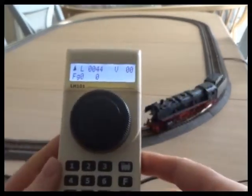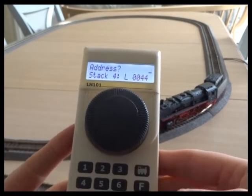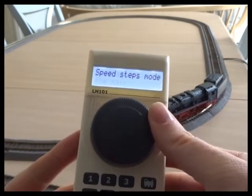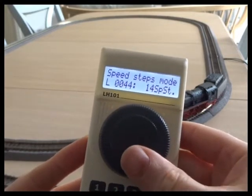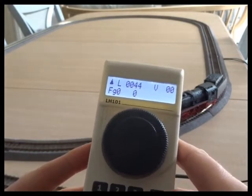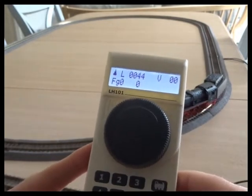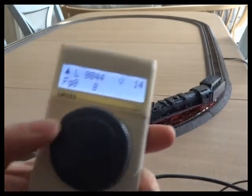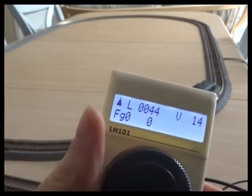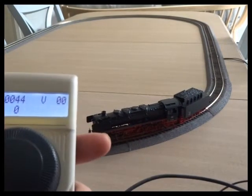So I can correct that in two ways. I can actually change the throttle so that it is selected for 14 speed steps, or I can change CV29 back. So now my throttle only goes up to 14, but my locomotive lights and everything are correct.